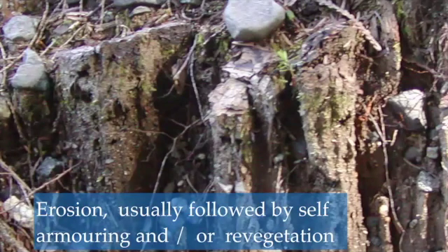In the first season, you will get a lot of erosion from a cut bank. The second season, substantially less. And by the third or fourth season, between revegetation and the self-armoring from rock and material, the sediment erosion becomes negligible. This is why, in the first year of road construction, what happens to ditch water capturing cut bank material is very important.